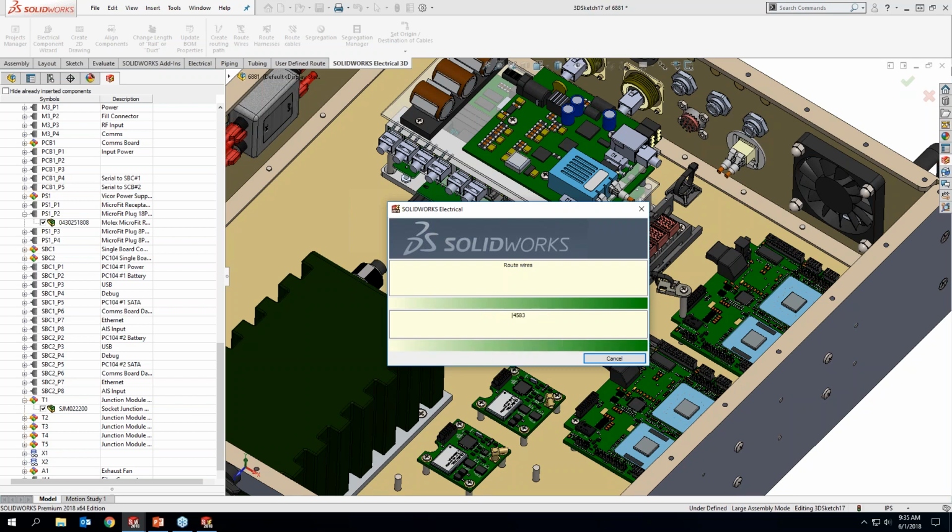It is a guideline that I've created as a 3D sketch to let my wires know, hey, I want you to try to follow this as best as possible. Because if you don't follow this, it's just going to go ahead and route wherever it wants, through everything, through a wall. So I've set this up so that it can try to follow it as best as it can.